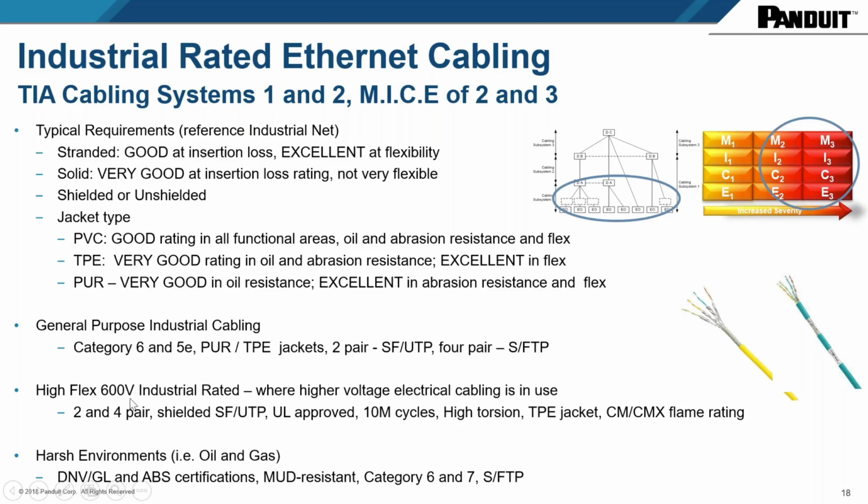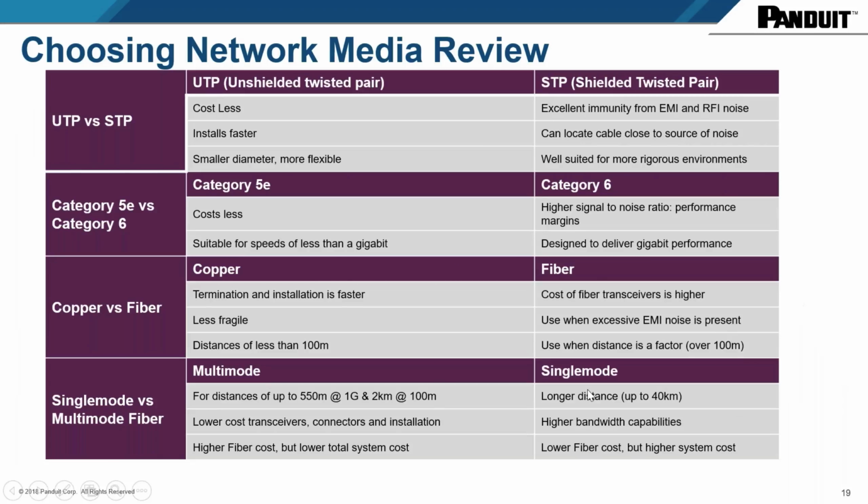When you have high flexing, you have to have different patch cords that can be rated for high voltages around them. All these cables are designed to handle 24 volt, but with the right shielding on the cable, it can be run next to a 600 volt line of power. So that brings me to this table.